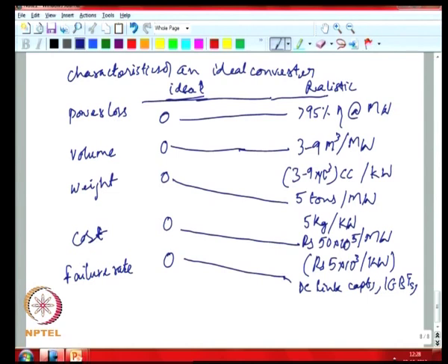You might have circuit breakers, contactors which have a defined number of cycles before they need servicing. You might have connectors which might experience fatigue after so many mechanical cycles. So you have equipment where the failure rate is not 0, it is finite. So depending on the particular application, one can try to back calculate what your failure rate is and what could be potential replacement durations within your equipment.